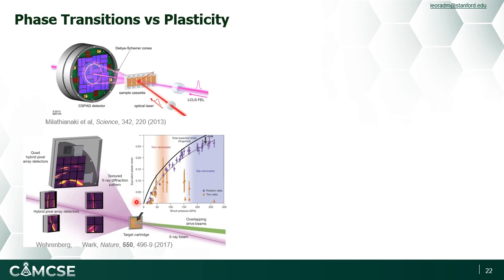When we push them at 10 to the 9 per second strain rates, in fact, what we typically find is that they actually can't quite deform that way fast enough with enough energy. And therefore, they often start with twinning, which is a lower energy mechanism, before they actually start to then become dominated by slip or dislocations.